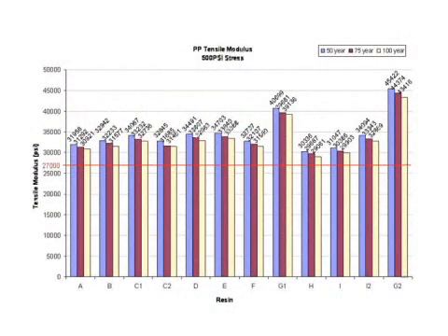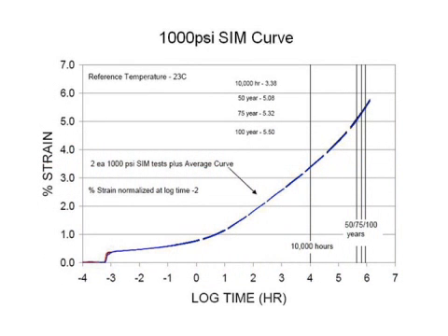As with short-term material properties, ADS has evaluated a number of resins for long-term conditions as well. In this particular chart, you see a design stress of 500 psi, and the resins that are represented there range from virgin resin pigmented to actual pipe samples, each of which exceed the 27,000 psi long-term flexural modulus. ASTM D6992 allows us to determine the long-term flexural modulus, but it also allows us to evaluate the long-term ultimate tensile strength. As with flexural modulus, ADS uses a conservative 100-year design service life value of 1,000 psi for ultimate tensile strength.